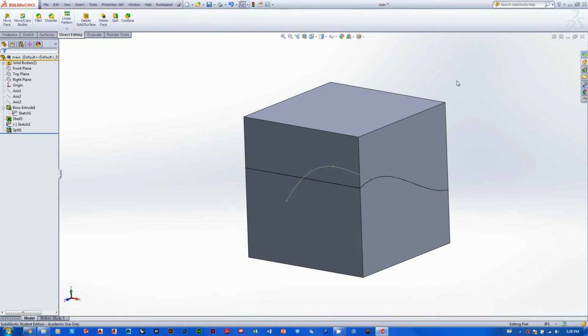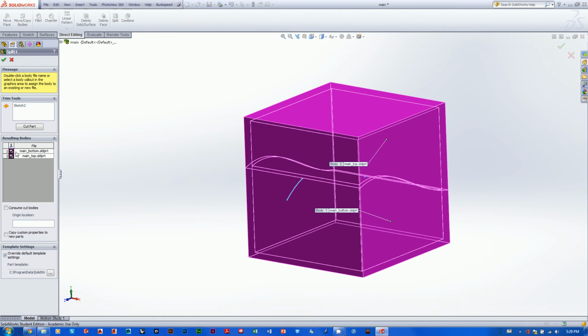This is going to be our master file. Because we hit those two black checkboxes that I just showed you in our split feature, these two right here, we now have created a link between this file here and those two other files. So anything we do to this file will now be updated in those other two files. Let me show you what I'm talking about.